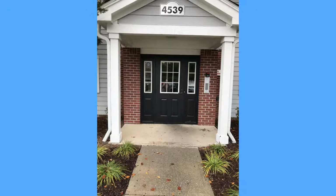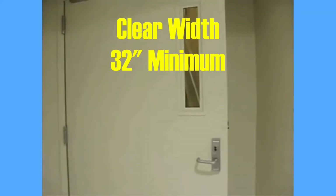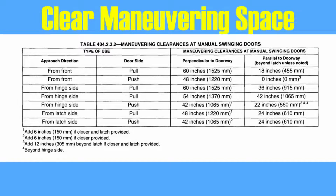Vision lights and side light glazing must be a maximum 43 inches above finished floor. Automatic and power-assisted doors shall provide a minimum clear opening of 32 inches in the power on or power off mode. That includes all leaves in a door system in the open position. Automatic doors and gates require the same clear floor space for maneuvering clearance.